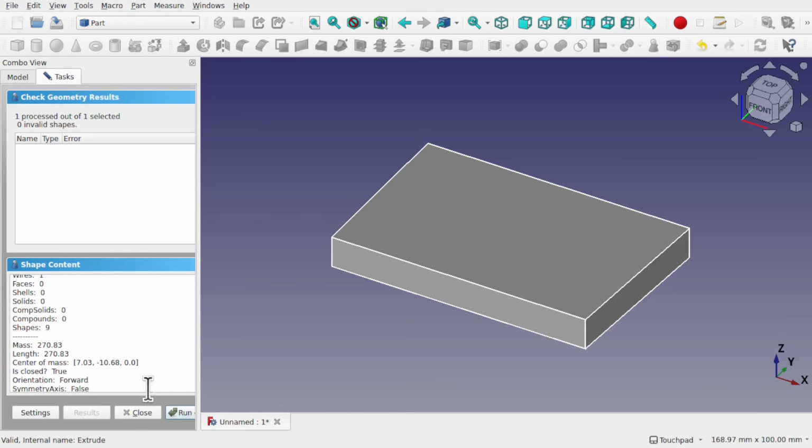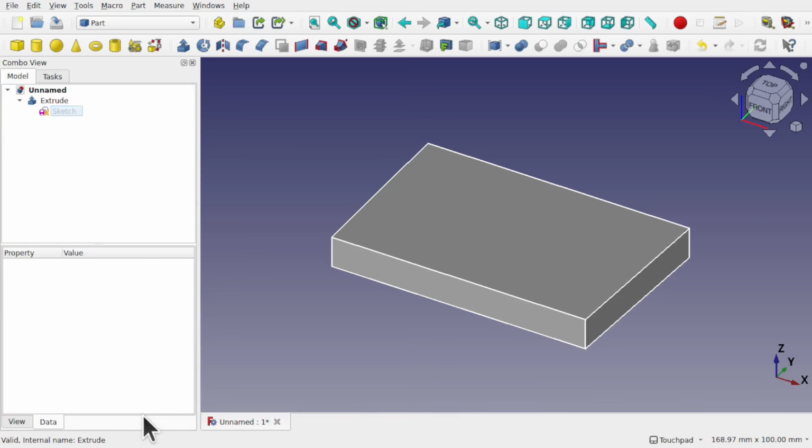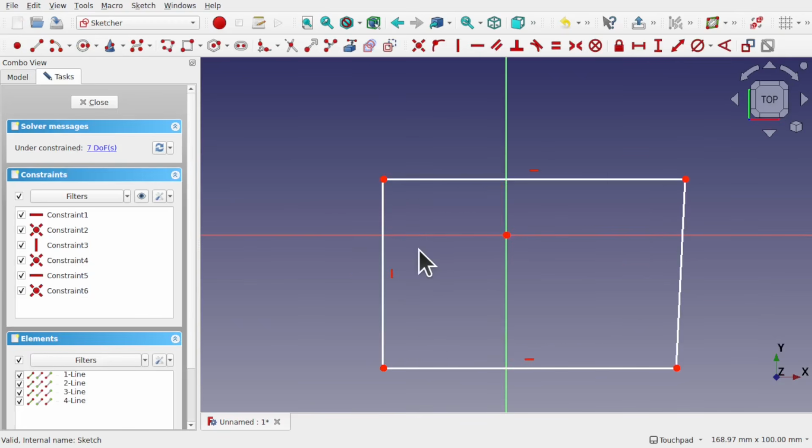And this is where the errors come into play. So if I looked at that sketch, it's a valid sketch, it's closed geometry. But you notice that this line I've got in here isn't quite vertical. So let's say I wanted to make this vertical. So I'm going to bring this in here. So you can see that's almost vertical. So I'm going to click on it and use the vertical constraint.